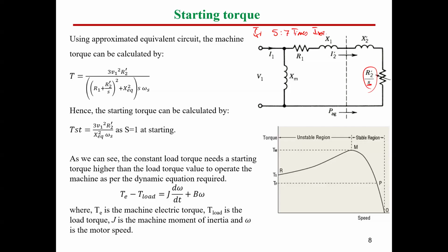The inertia of the motor is the mass of your rotor. So this is going to be a huge mass to be moved, and this is going to take very high energy in the starting. Once you rotate this big mass, you don't need any high power anymore to run your motor. For that, the starting current of the induction motor is very high.